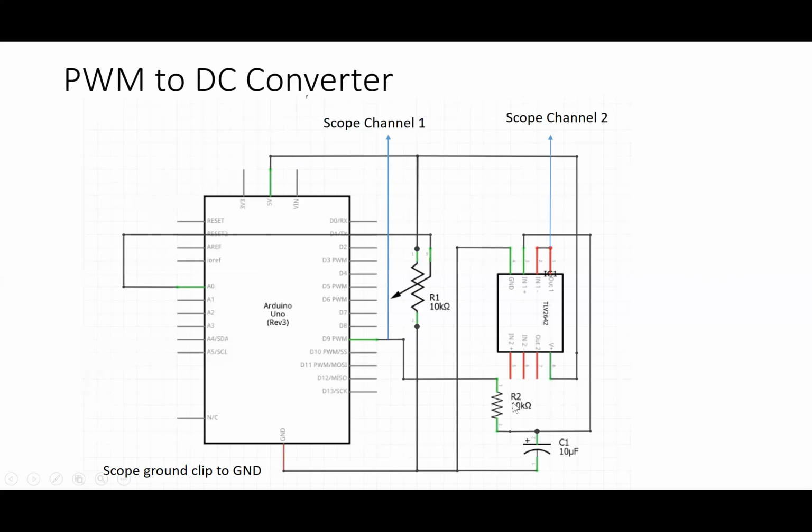And then, because this would have a high Thevenin equivalent resistance because of this capacitor, we're going to use our op amp to generate a low Thevenin equivalent resistance output. We put this DC voltage now into the non-inverting input of our op-amp. We have the output and the inverting input connected together. We hang our scope probe on the output and we supply power to the op-amp just as we did before.